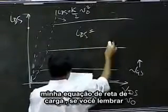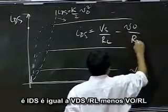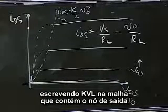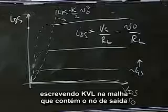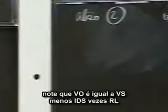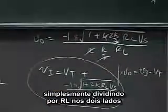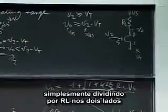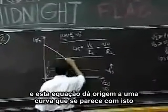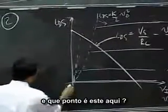My load line equation, if you recall, was IDS equals (VS minus V naught) divided by RL. This was simply obtained by writing KVL at the output, at the loop containing the output node and the supply VS. Notice there that V naught is equal to VS minus IDS times RL. Okay, and that's simply by dividing by RL on both sides and moving IDS to the left-hand side, we get this equation. And this equation gives rise to a curve that looks like this.